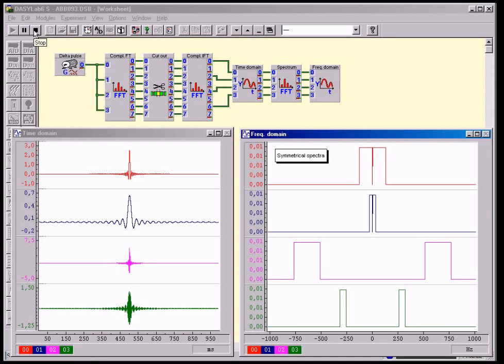The energy of the test signal should not be put in abruptly or in a very brief space of time, but continuously, so that the system cannot be destroyed. Please note in this connection that as a result of the UP, a limited frequency band signal must have a certain duration, delta t. The maximum value of the test signal cannot be so large that the microelectronics are destroyed.